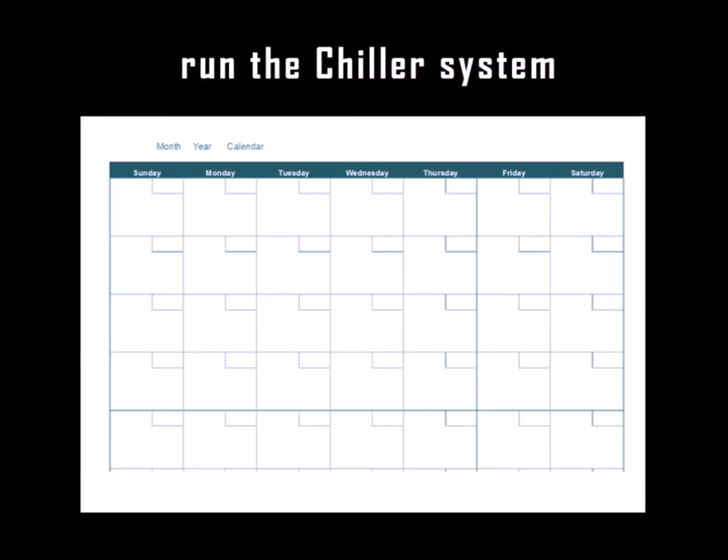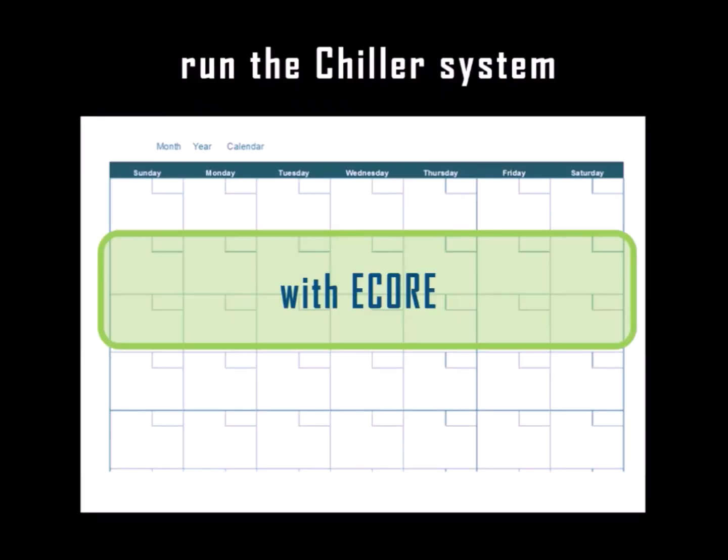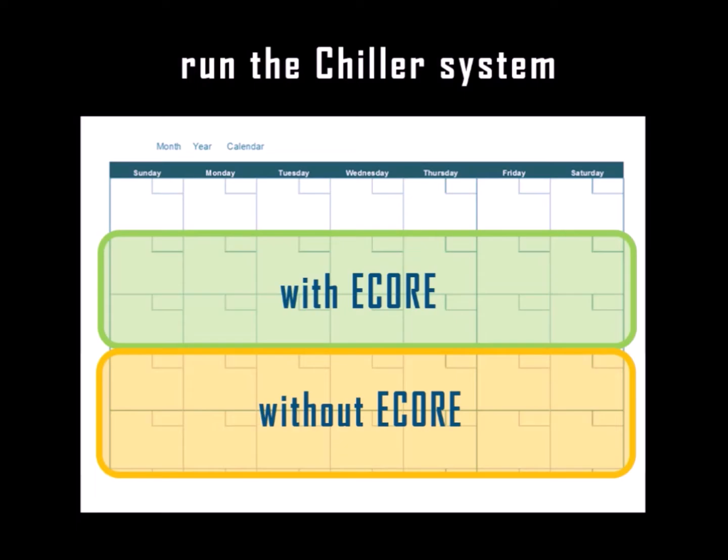That's great to hear, because sometimes, for example, I'm just envisioning a hospital that might have opened a NICU wing for the children, and what ends up happening is they use more energy in one particular area. So the level setting becomes just something you have to mutually agree with the customer, I guess, that you're measuring the same things. Correct. And if there are too many changes in the facility, one other way to simply measure the savings is to run the chiller system with our technology for 2 weeks of the month and run the same system without our technology operating for 2 weeks of the month. This is something we've done to actually show the significant difference in the consumption with and without our technology.